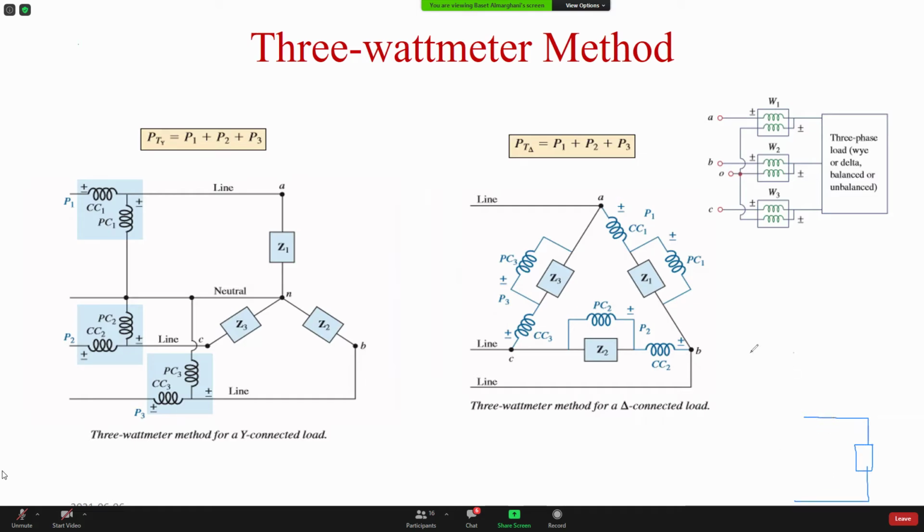So what you do, you bring your watt meter. The watt meter measures the voltage and measures the current. The way it measures the current is like an ammeter exactly. So you insert it in the circuit. For the voltmeter, you connect here and the other one to measure here. This is a watt meter.